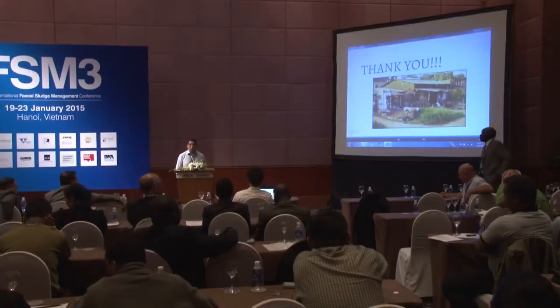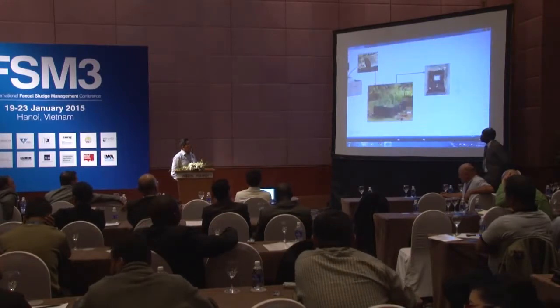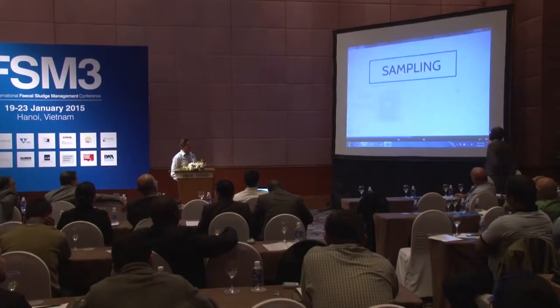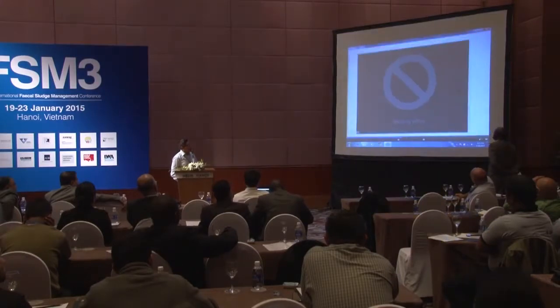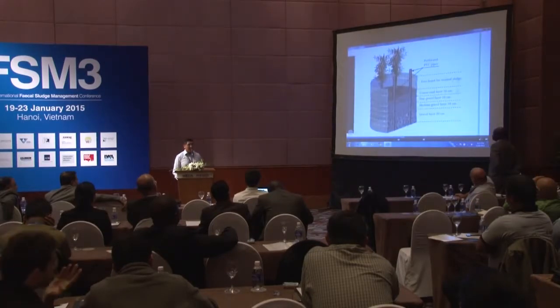Okay. About the configuration, I'll try to find the slide. But it's a general recommendation for designing these systems. I added one extra layer. Usually we just use 3 layers. In most of the experimental units, we usually recommend 3 layers of gravel, fine gravel, and sand between 10 to 15 centimeters. That's the most used range.